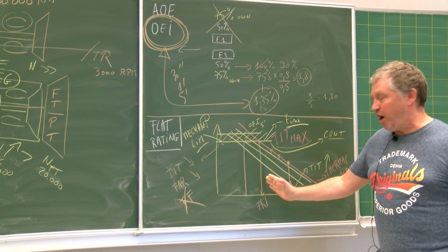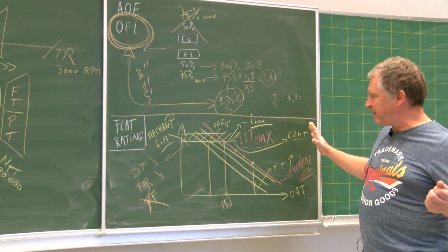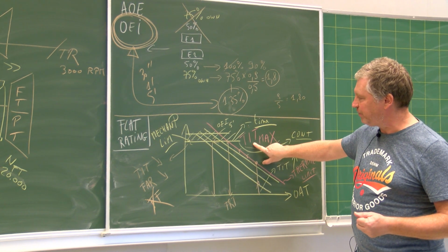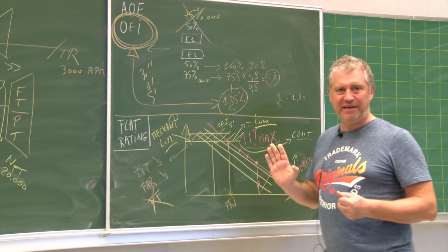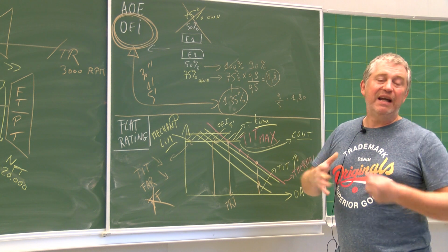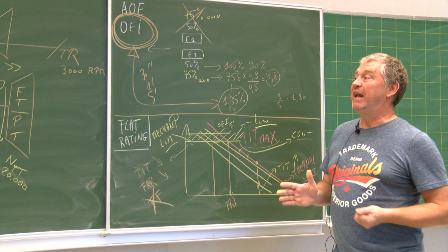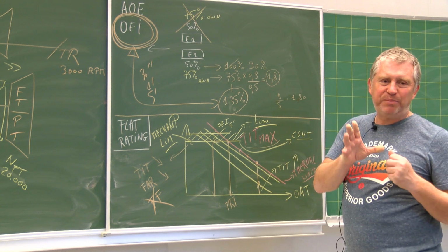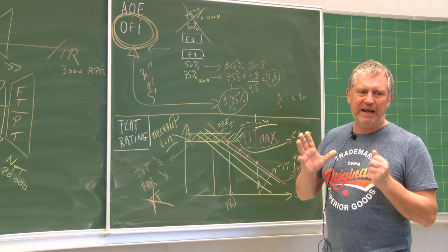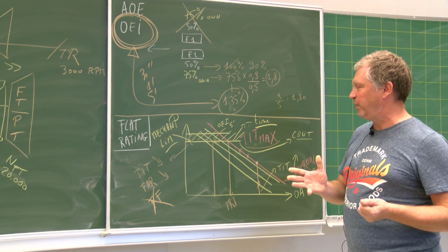One, let's say, on the right-hand side, is due to the thermal effects. This is related with the TIT max. And on the left-hand side, this is related with the mechanical limit with the gearbox and or the shaft of the engine. And that's why you use this term turbo shaft. This is an engine that is characterized mainly by its shaft and what the shaft is doing and by the limit that you have on the shaft.